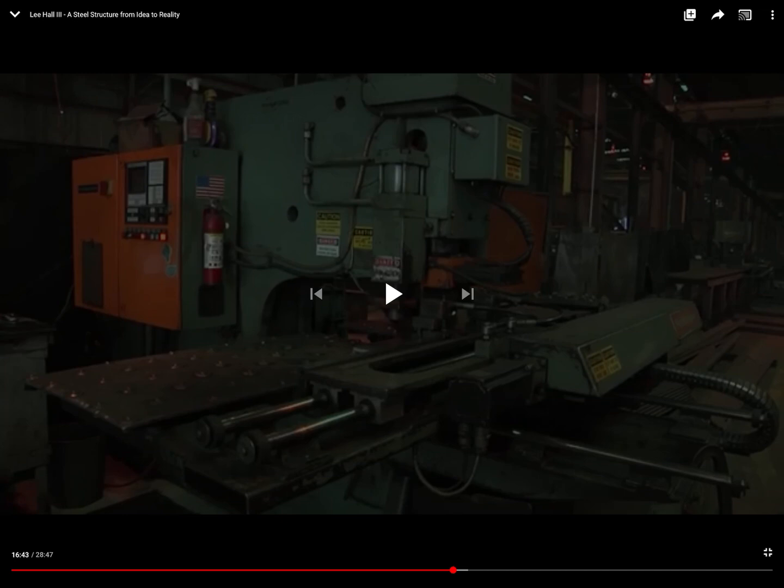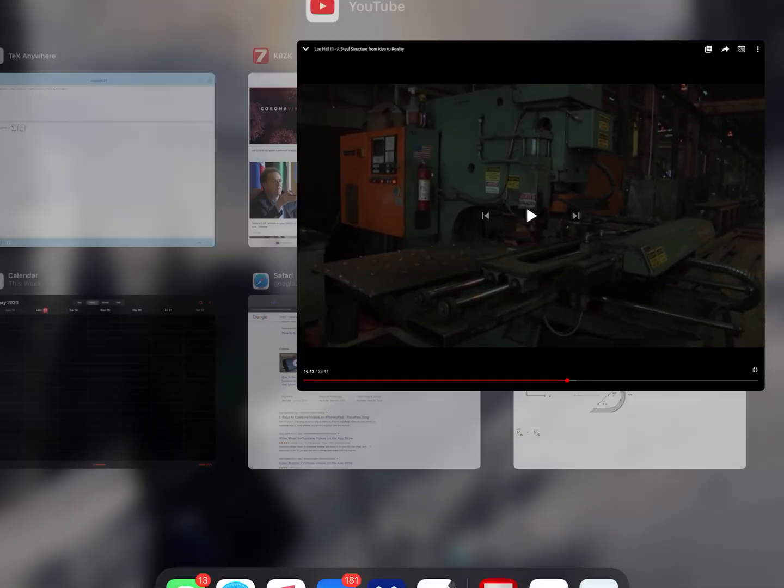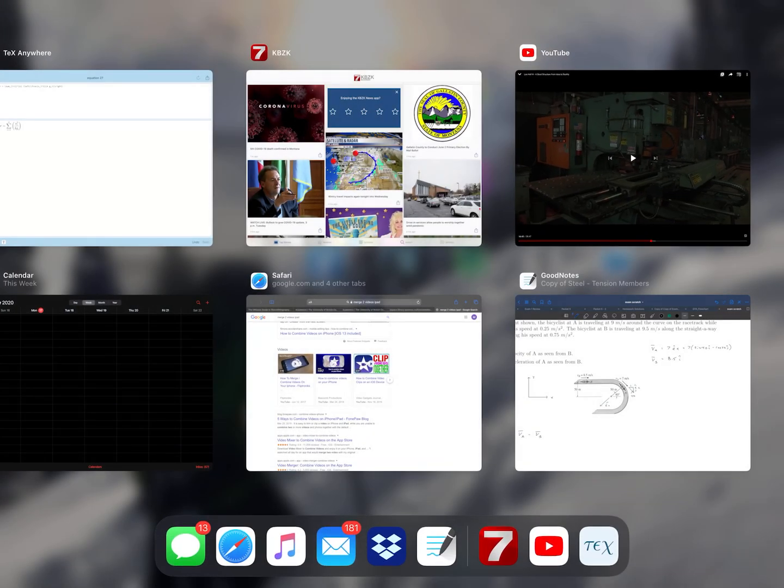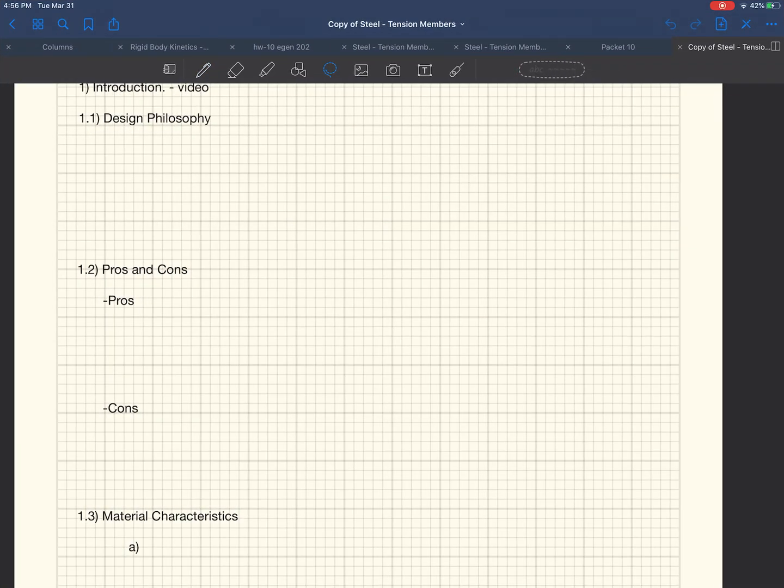And then you take that design, and then you need to come up with the steel. So it gets shipped off to a steel fabricator, okay? I'm not sure if that's going to actually show by trying to show a video and record it and stuff like that. So we'll come back over here. So it goes over to a steel fabricator. And then the steel fabricator says, yep, this is how we interpret what your design is going to be. And then they give you these things called shop drawings. They say, this is what we're going to make, right?